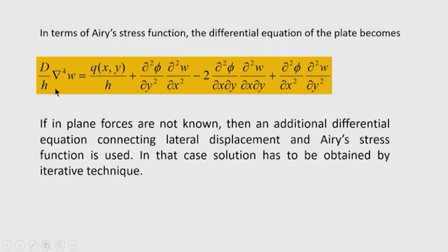So, introducing this quantity, now we can write this equation, the plate equation, in presence of the transverse load as well as the in plane forces, like this: D by h, h is the thickness of the plate, del⁴ is the biharmonic operator that consists of 3 terms.